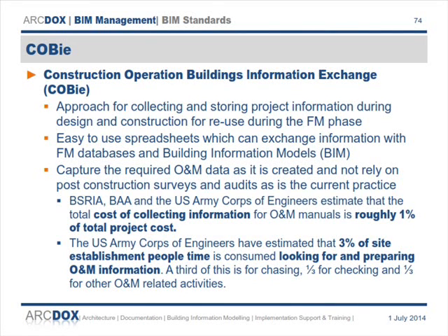US Army Corps of Engineers estimated 3% of site establishment people time is consumed looking for and preparing O&M information. I mean, crazy time. Again, if you can cut out all of that by making the information available, making other people collate the information. So in terms of COBie, what you want is for people who are responsible for their element to input the information that's required by COBie. So if you're working with a glazing contractor, you want the glazing contractor responsible for putting the information in about the windows. Your boiler contractor, you want them to be responsible for the information about the boilers.